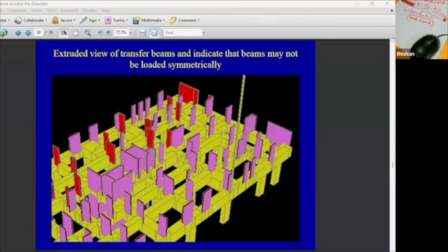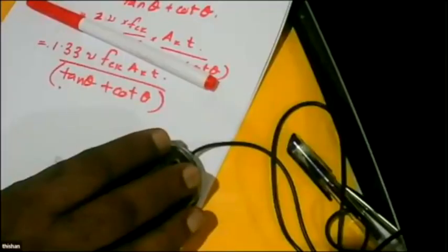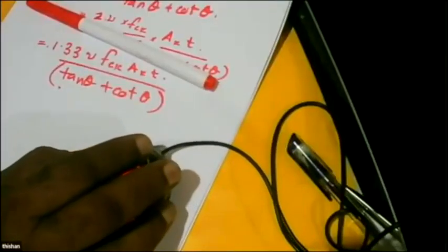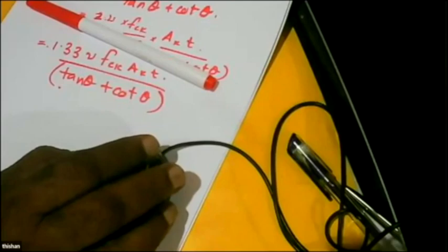Right. So, are there any questions, Bandhuka? Yes, sir. There's one question regarding this modeling. Isn't it better to have a shell element drawn to the length of the wall as a rigid arm, because a rigid beam may induce excessive torsion moment on the main beam?